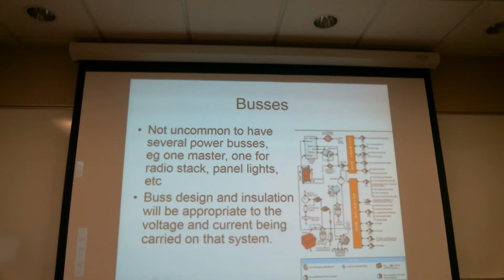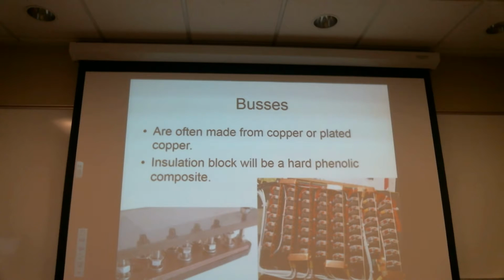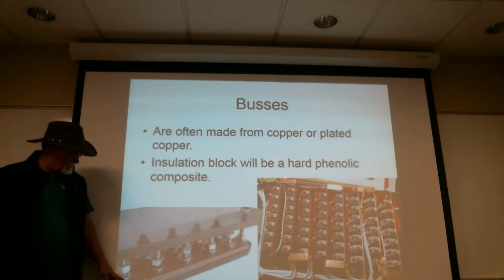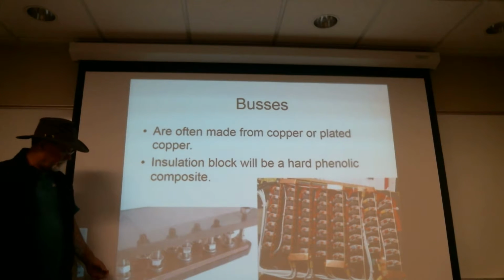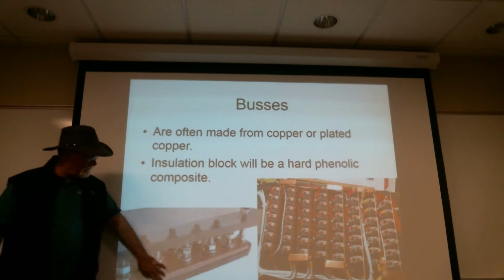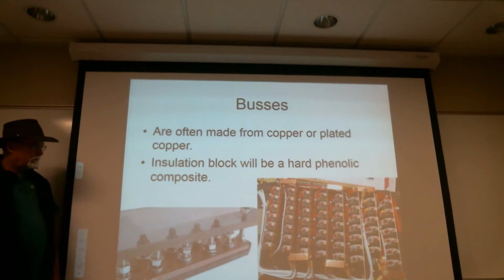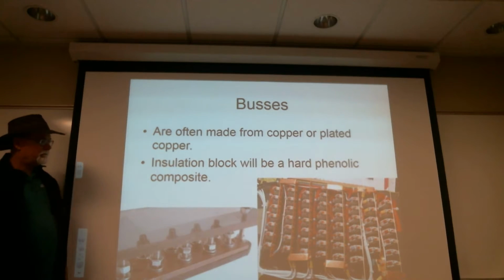And of course, obviously the bus matters both for current carrying capacity, so the physical size of the screws and the plates, etc., to handle the current, and as well how well it's insulated from whatever it's attached to, so that if it has reasonably high voltage, the voltage isn't going to leak and go someplace it's not supposed to go. So they typically are made from copper or a plate of copper. In this case, somebody put a bunch of probably threaded studs from the backside and then mounted that onto a plastic plate. And they even made a nice little cover over it.